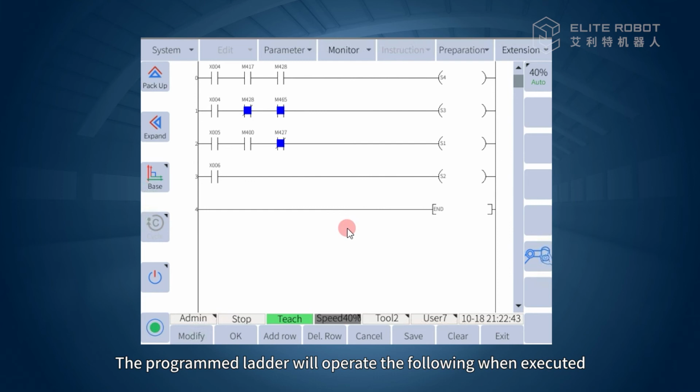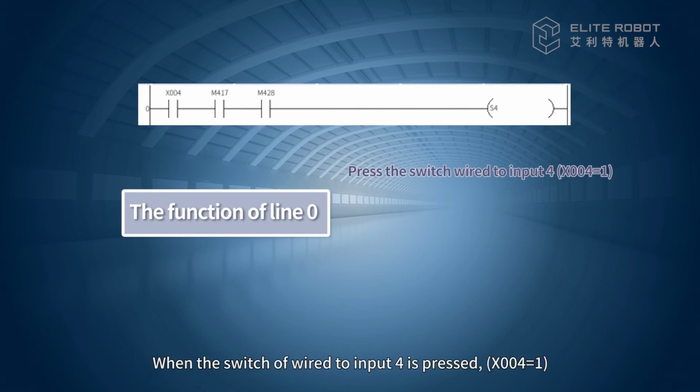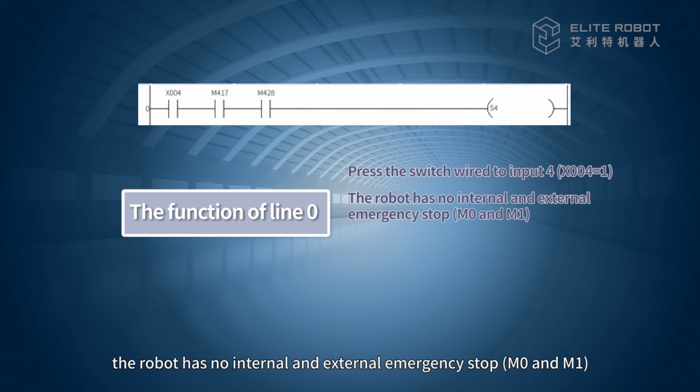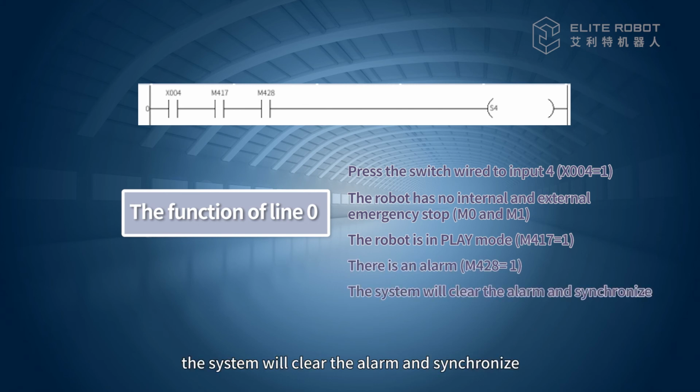The program ladder will operate as follows when executed. The function of line 0: when the switch wired to input 4 is pressed, the robot has no internal and external emergency stop, and the robot is in play mode and there is an alarm, the system will clear the alarm and synchronize.